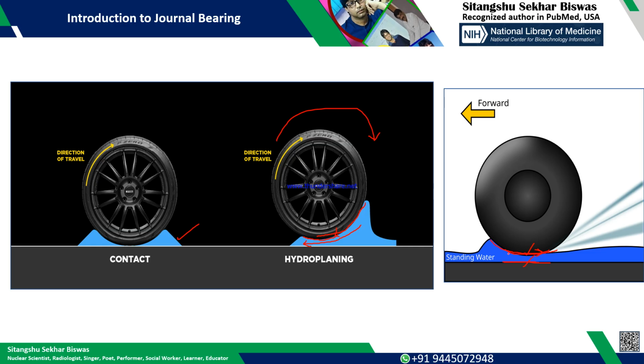As per Bernoulli's equation, where the dynamic head is more, the static pressure will be less, and where the dynamic head is very low, the static pressure will be high, and due to that there is a lift.